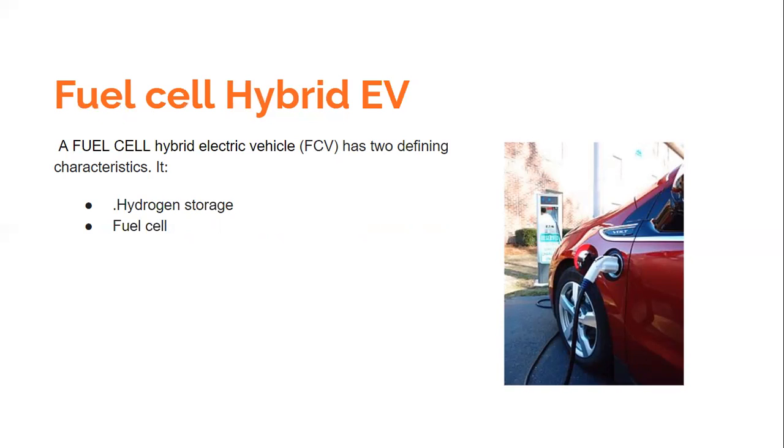However, these fuel cell hybrid vehicles are a bit costly. The typical cost is about $200 per kilowatt, which is far greater than the conventional EVs and also the ICE engines. As I said, there is an issue related to safety in case of flammable hydrogen leaking out of the tanks. Once these obstacles are overcome, FCVs can outshine battery electric vehicles in the future.